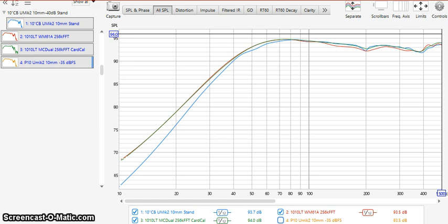But if you take a look, of course, at the low end, by the time you get down to 20 hertz, it's 3 dB difference and increasing. The thing is that this is a closed box 10-inch woofer. It can only be a 12 dB per octave asymptote. That's the only possibility with a closed box system. That's why I used this initially to make some comparison tests, because I know what the response should look like. Whether or not it's absolute doesn't matter.